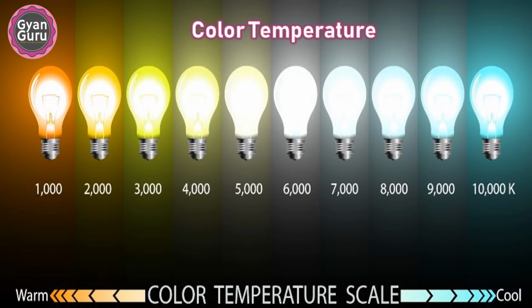Many designers or customers really enjoy warm tones that match up to incandescent light bulbs, which fall into the 2700 Kelvin to 2800 Kelvin range. LED bulb color temperatures from 2700 Kelvin to 2800 Kelvin are commonly used in restaurant lighting, residential lighting, hotel walkways and rooms, and spaces where a warm ambience is needed to set the mood. Cool white ranging from 4000 Kelvin to 4300 Kelvin is also very popular in offices and commercial buildings.